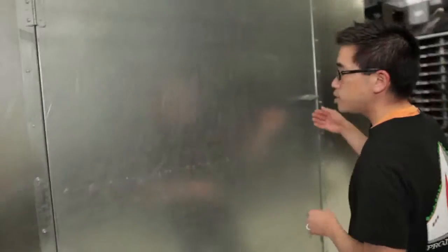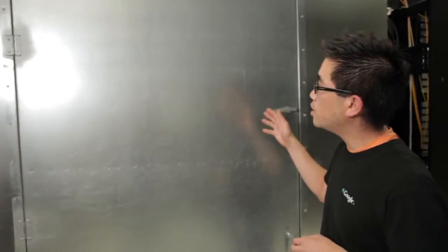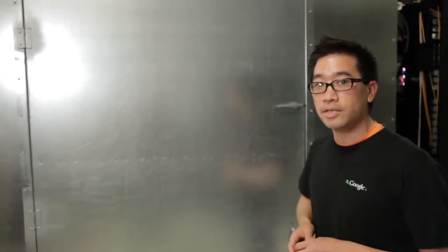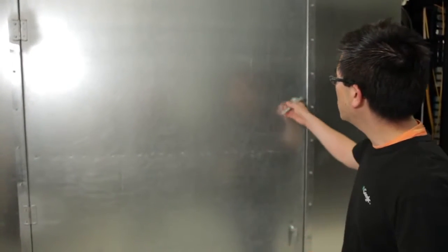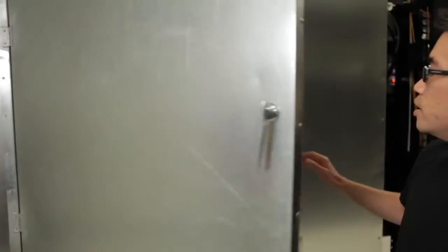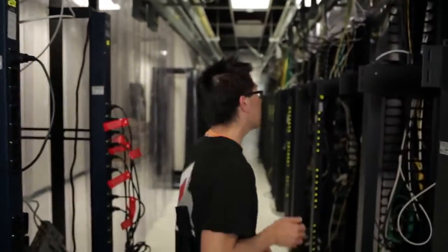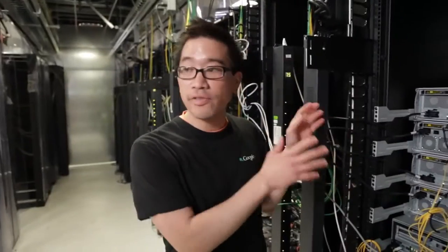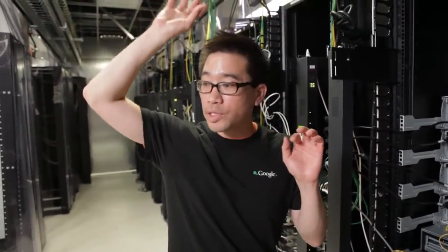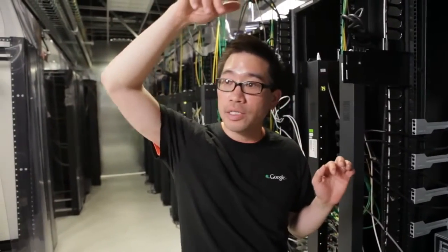We are set now to enter the hot aisle containment door, and we incorporated simple, inexpensive sheet metal doors to separate very tightly the cold aisle from the hot aisle. Now over here, the hot air from the racks is coming up, going overhead up through the return air plenum, back to the CRAC units to give you a nice high temperature differential across your CRAC units.